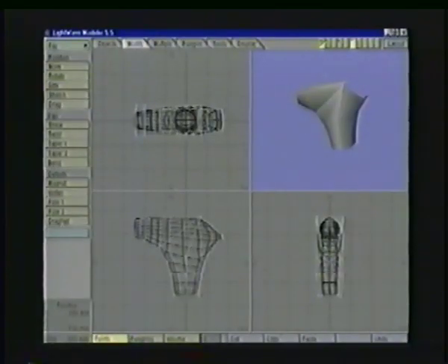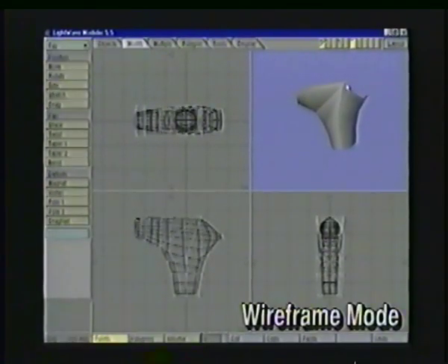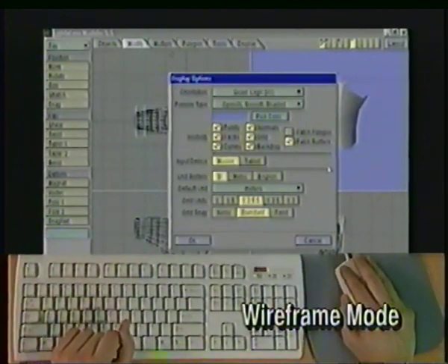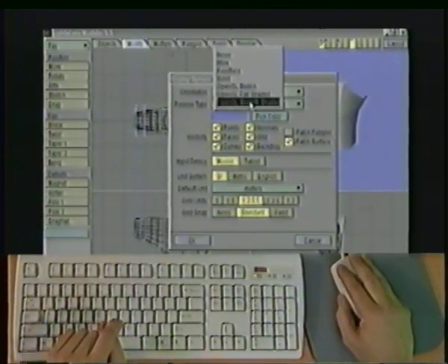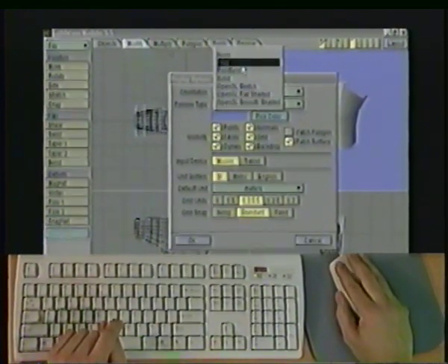Now, this is going to be an interesting thing. First of all, I need to select just the 4 points on the back end, but I can't just drag across them. I need to select them in order. So I'm going to go to wireframe mode. I can get there by hitting D for my display options, and instead of OpenGL Smooth Shaded, I can go to wireframe mode and say OK.